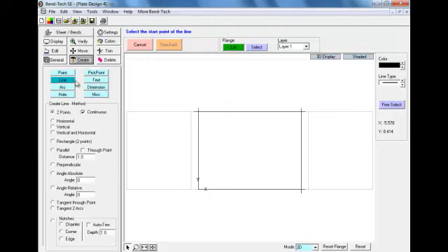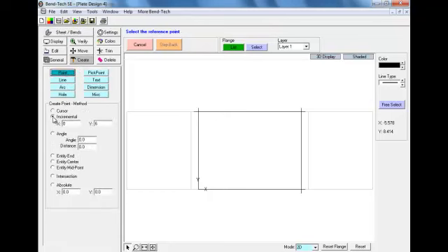Our first point is going to be created using the incremental version, and it is going to be 3 inches in the X field. We're going to add 3 inches in the Y field, and we're going to create a point in that location on the base flange.